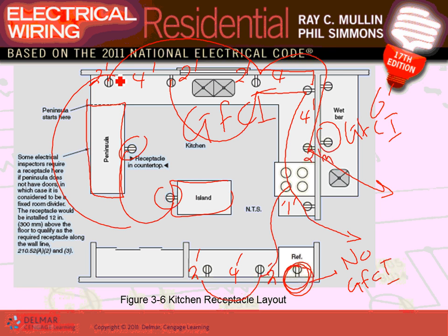Two circuits to the kitchen. But the two circuits have to go and power equipment on the countertop. Any comments, any questions? Chapter 3, guys, has all the information that you need for laying out your receptacles. So it's so important. So kitchen, three things for the kitchen, guys.